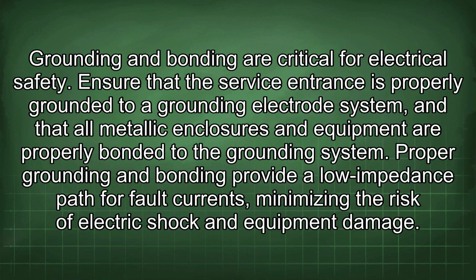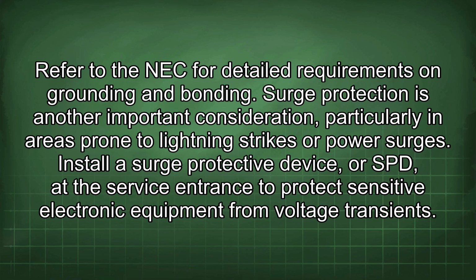Grounding and bonding are critical for electrical safety. Ensure that the service entrance is properly grounded to a grounding electrode system, and that all metallic enclosures and equipment are properly bonded to the grounding system. Proper grounding and bonding provide a low impedance path for fault currents, minimizing the risk of electric shock and equipment damage. Refer to the NEC for detailed requirements on grounding and bonding.